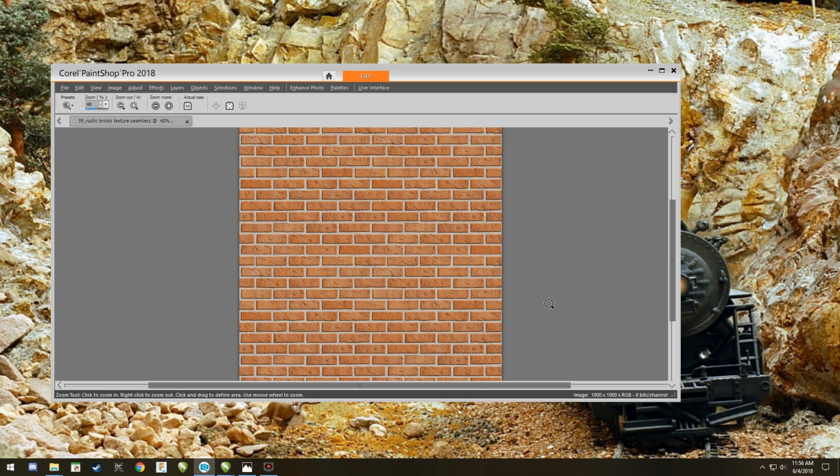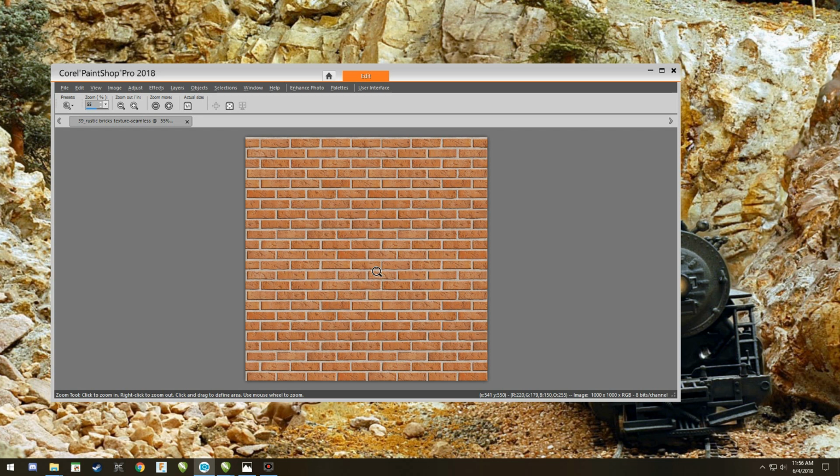So the first thing I'm going to do, this is the color image, and the computer understands grayscale. You can use the color images, but it's a little more challenging because the laser needs to have each color assigned a power that it's going to use. So turning it to grayscale makes it easy because you're only dealing with gray, and then darker ends are going to have more laser power, where lighter ends are going to have less laser power.